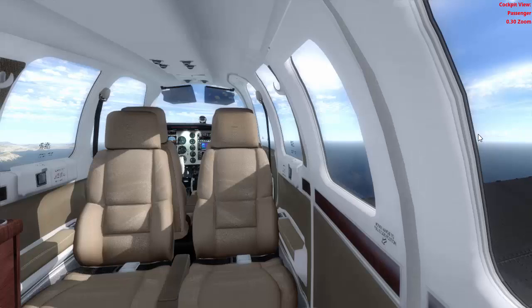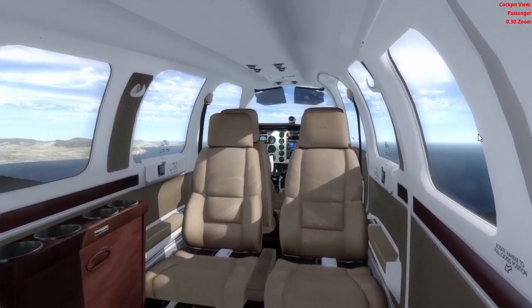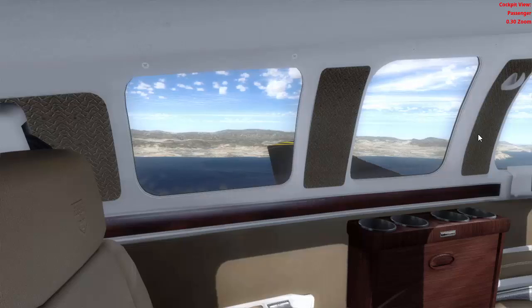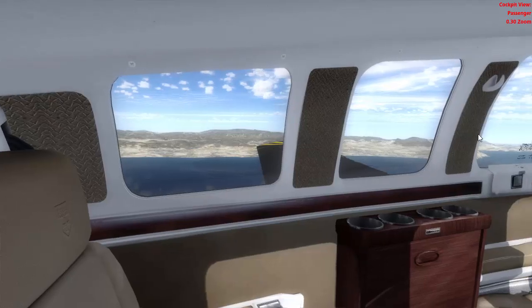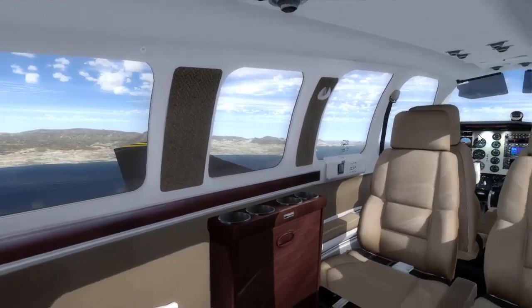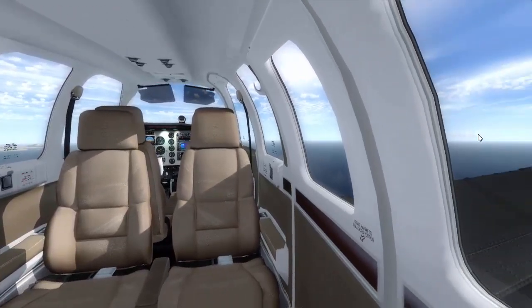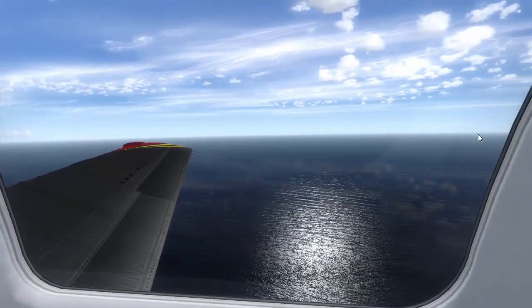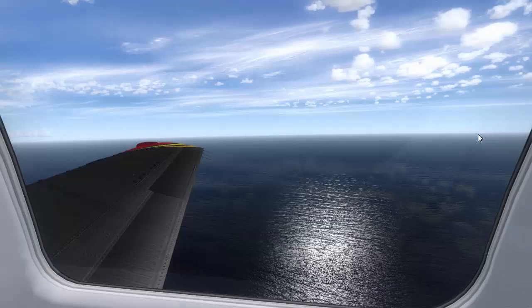Something fatal is you do not descend with a proper configuration of flaps, with proper flap settings. Something fatal is that you do not set up properly the configuration for your aircraft to take off, and you apply full flaps, for example, when you don't have to apply full flaps, you don't get enough speed, and when you ascend, you're entering a stall and you crash miserably and you die. Those are fatal settings, okay? But if you get confused by just one knot, you won't die, for God's sake, okay? And this is only a simulator, remember that.